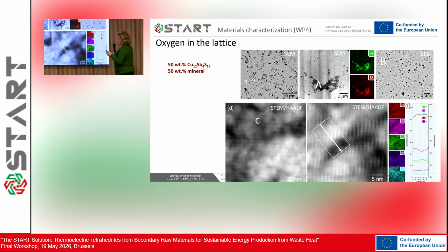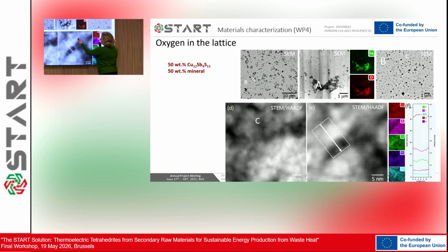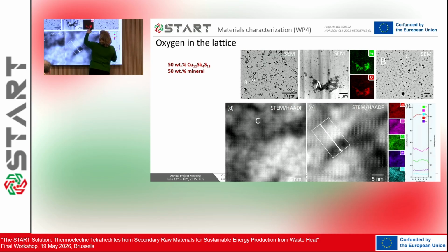Then we also see oxygen. In this case, we had 50% synthetic, 50% mineral. These big things in the SEM microstructures are iron oxide. But if you zoom in here, what you see is this. It's full of pores again. And if you zoom between the little pores, you see this very strange contrast. And if you do EDS, you see that what you have is iron and oxygen.